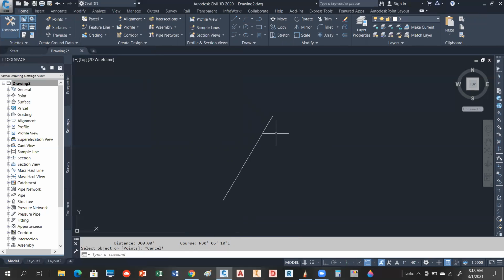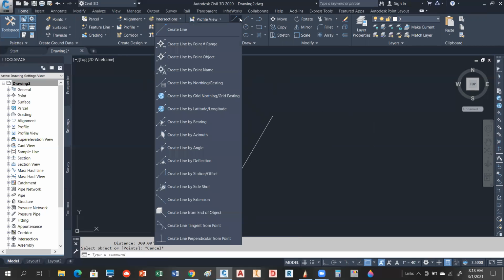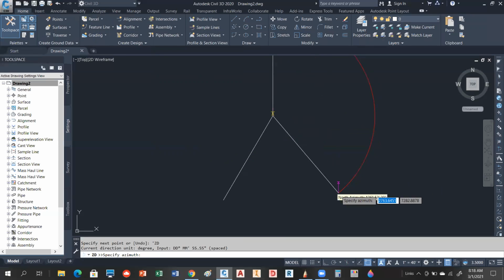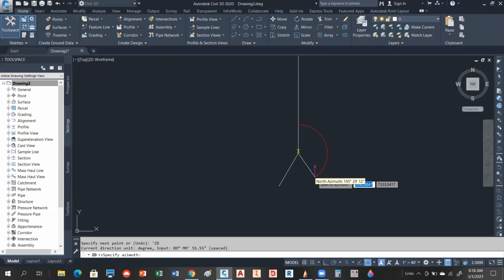Equally, I'll show you if we do a bearing, excuse me, an azimuth. I'm going to create an azimuth from a line. I'm just going to snap to the endpoint of that line. And notice it gives me the azimuth tool. So you have to remember, this is based on what's called azimuth north, and that would be an ambient setting. If you were using azimuth south, you could switch that. So it's projecting that into the north direction, measuring the angle off of that.